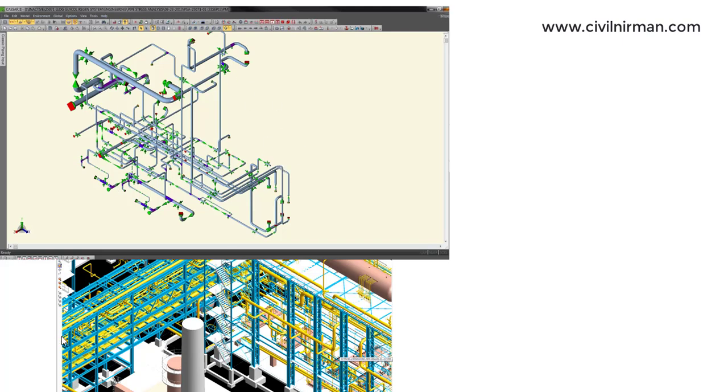Now as you can observe over here, I have considered one typical 3D sketch. Now see, in most of the multinational firms, all the information related to the 3D modeling is performed in S3D software, where all other disciplines are also working together in order to model every component, whether it's your cable tray, pipes, everything. So the piping discipline will model their pipes in the same software. Similarly, other disciplines like instrument and electrical will also parallelly model their segments in order to track everything which is aligned with the structure discipline as well.